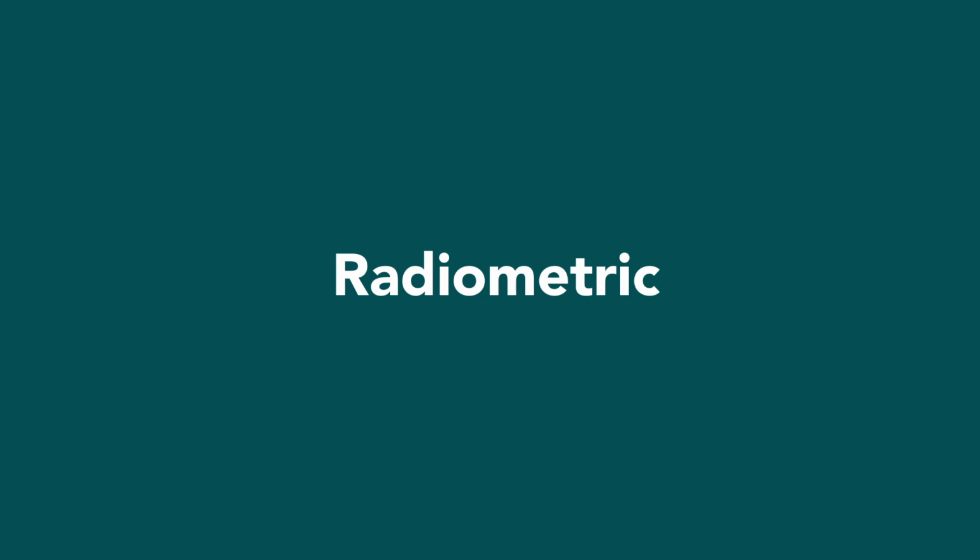The next one we've got is radiometric. So radiometric is basically a term used to describe thermal images that have temperature data encoded in them. Some cameras are radiometric in nature. Of course, I'm talking about thermal cameras over here. Some cameras are radiometric, which means that they can store thermal information or temperature information, and therefore they can be used for temperature analysis. Whereas other cameras actually don't have this property, and therefore they can't be used for temperature analysis, even though they might be okay to use in a search and rescue context. So radiometric is another important term to keep in mind.